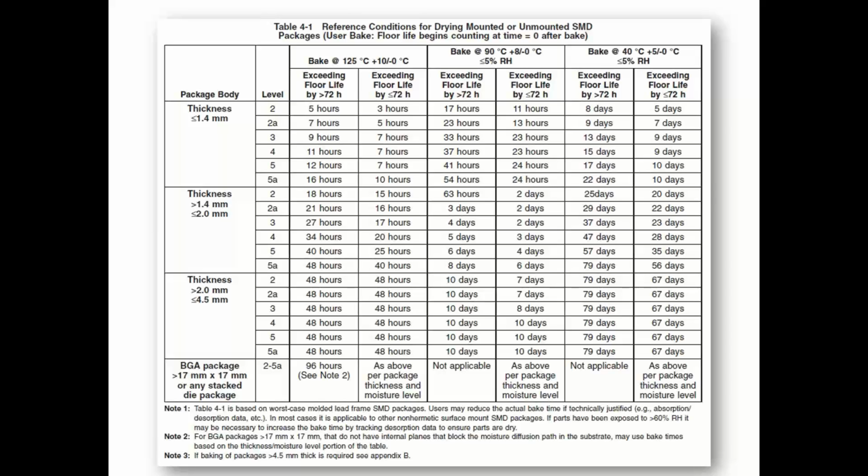And these times that we quote are related to the exposure time. So if you've got a board with components which have, let's say, 10 hours open time, you've opened the parts, you've placed them on the board, you've reflow soldered them, and then you're going to go on to a second side reflow, but you're delayed for a week, then clearly those components are outside of their process cycle. You have to decide what you're going to do. And this is one area which quite often is not that well defined within companies. It's not just the time the components are exposed before you solder them for the first time. You've also got to think about the second time you might be attempting to solder that board.